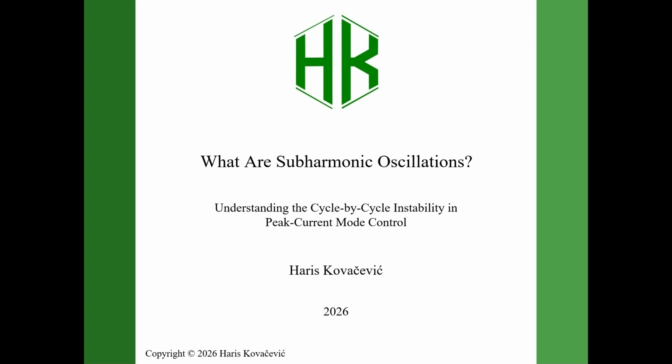In this video, we will answer those questions. We will look inside the peak current mode modulator, understand how small perturbations propagate from one switching cycle to the next, and develop a simple discrete time model that explains the origin of subharmonic oscillations. Once we understand this mechanism, the famous 50% duty cycle limit becomes almost obvious.